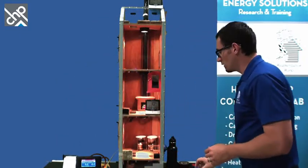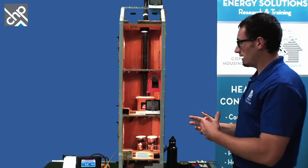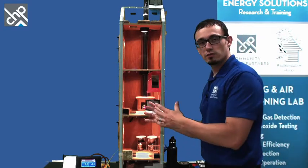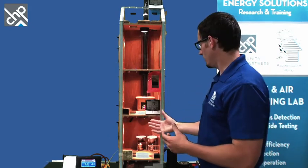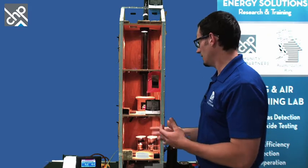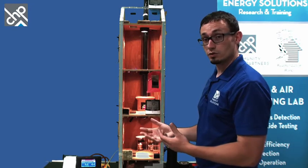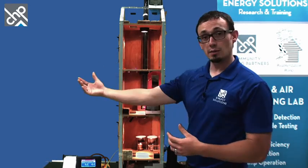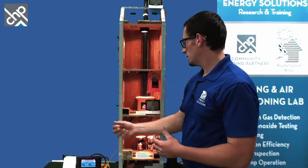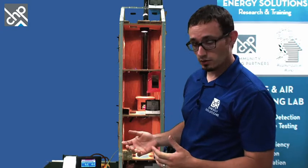So we've shown you the heat moving out of the building due to that temperature difference, 150 degrees inside, 80 degrees outside. That's a massive temperature difference, 70 degrees. That's going to be a huge driving force for us here. So that heat that's building up inside the house wants to readily escape to the outside of the house. So that's conduction, the first mechanism of heat transfer. Does anybody remember the second one?